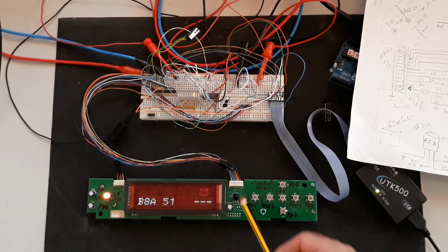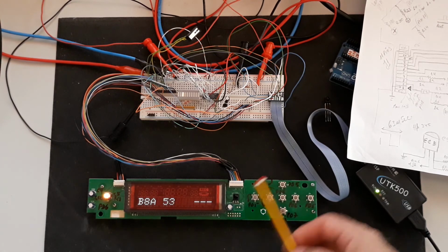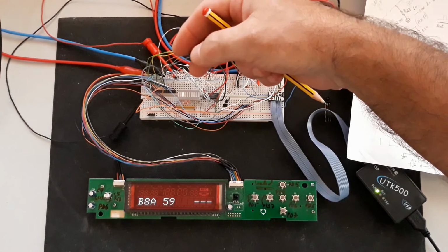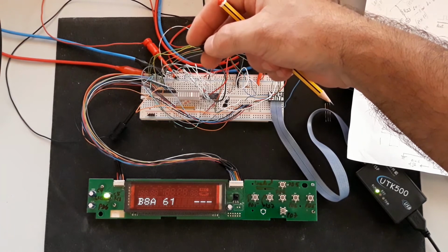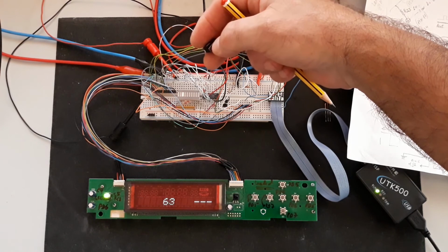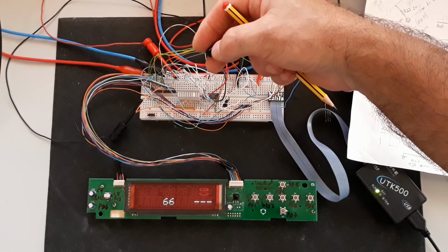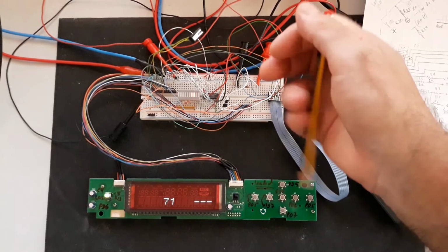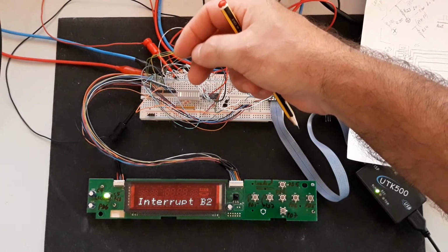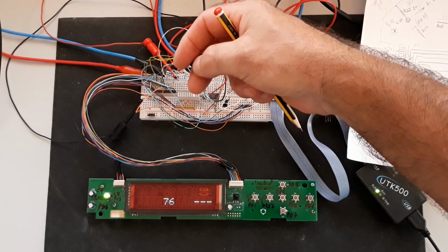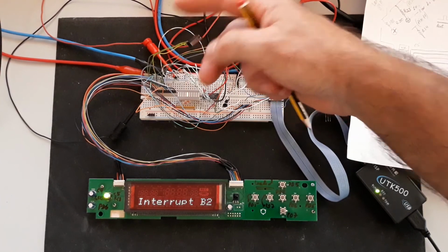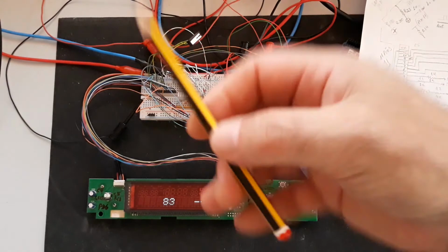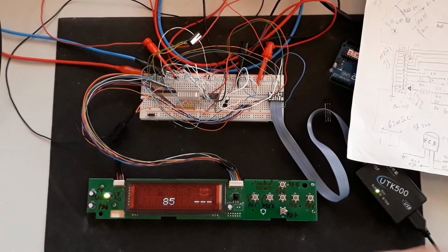Also, I have implemented a count here. Also, I have implemented the reading of the keys, this key and this, a total of 8 keys. Also, I have implemented an external interrupt here. Each time I press the button, the state of the switch changes and starts the interrupt, okay? If I press, release, press, release, press, release, okay? Each time the change happens, up or down, the interrupt takes place.